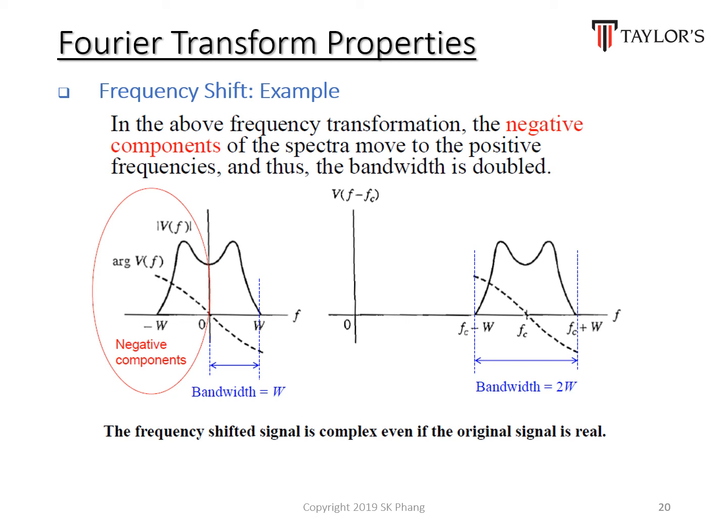So sometimes when you have a certain time domain signal, in frequency domain it will span through zero, negative omega, and positive omega. Because of the properties of the frequency domain, it will be even symmetric, meaning that those on the left will be the same as those on the right. But which means that it limits our bandwidth to just the omega. So let's say sometimes we want a higher bandwidth for our signals to be sent through.